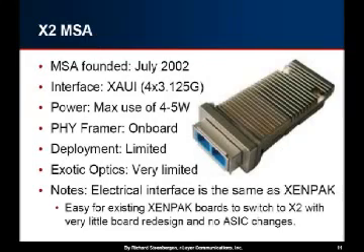So then there's the X2, which is basically an evolution off of Xenpak. Electrically, the connectors are exactly the same. So anything you can say about Xenpak, you can say about X2, except it's smaller and draws a little less power. But it's the exact same hardware, implemented the exact same way, but you can get a little higher density out of it just because it's physically smaller. And it's not very common right now.